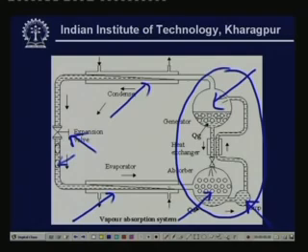Now when this vapor comes in contact with the absorbent in the absorber, since the absorbent has high affinity for water, it absorbs the water vapor. That means this absorbent continuously draws the water vapor from the evaporator. So you have continuous generation and continuous withdrawal of the water vapor from the evaporator. This is like the suction of a mechanical compressor. Then, as the absorbent absorbs water vapor, it becomes strong in refrigerant. So we have to make it weak again. So how do we make it weak?